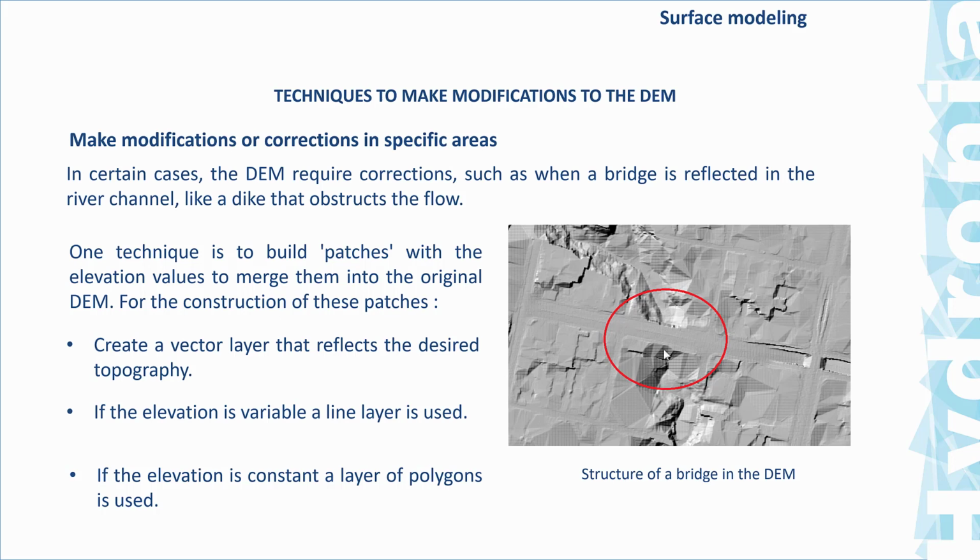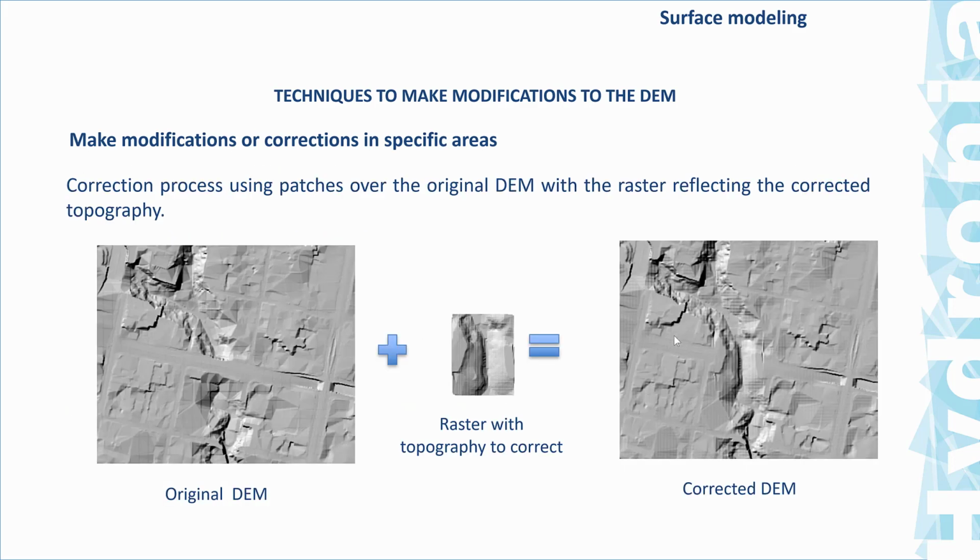If you were to use this data in HydroBID Flood, what will happen is that if you have flow coming from upstream here, then it will treat this as a dam because it's damming the stream. So you need to remove these elevations from the terrain in order to have a terrain that represents the flow surface and not the bridge surface.